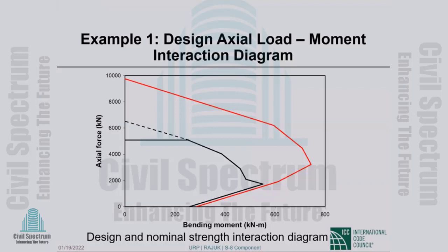And even when not required, it is not a bad idea to do that. You don't have to go too deep, but something like 12 inches is a good idea. Sometimes it is 12 inches or one development length of the largest longitudinal bar, however much that is.